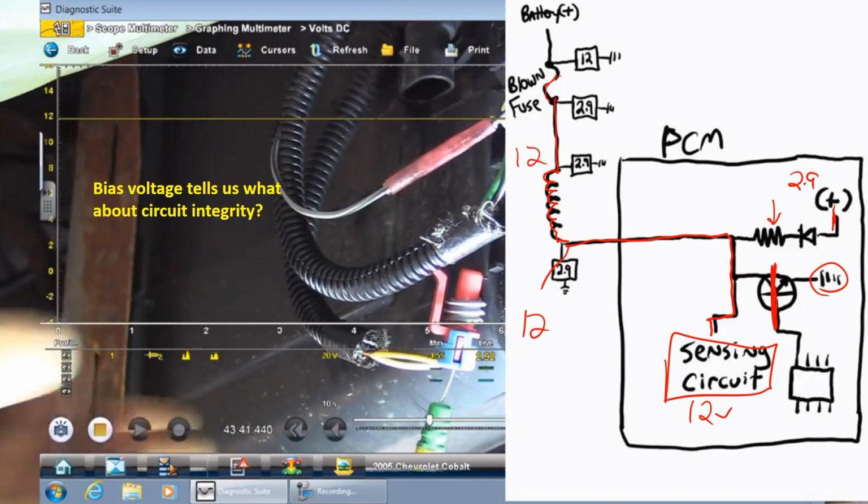And then it goes this way. It tries to flood this resistor. What is that guy? It's a diode. Guess what? Can't go that way. I'm not going to hurt anything else. So if it's 2.9 on the other side, that answers our question as to why wouldn't the 12 volts overcome the 2.9 and cook something that direction. We'll just put a diode there.